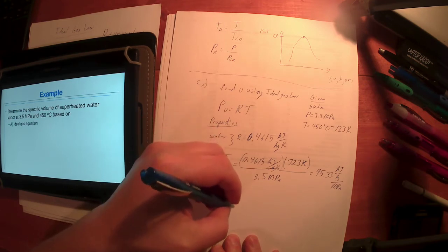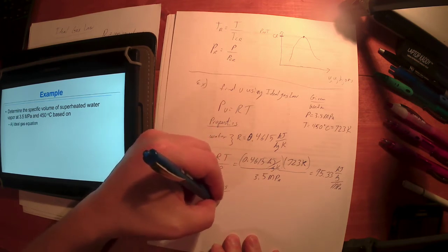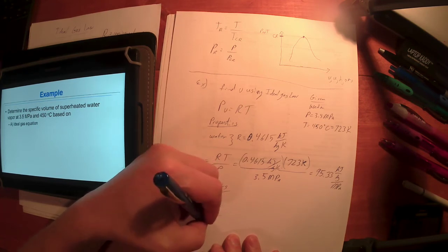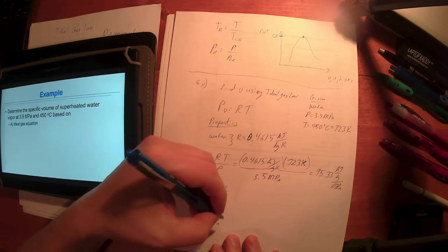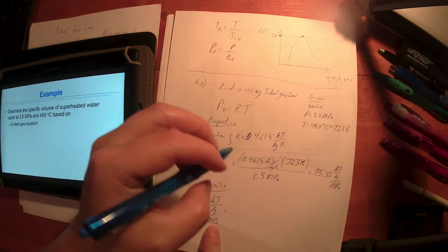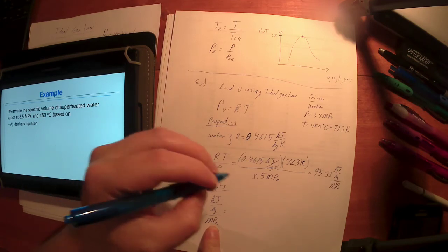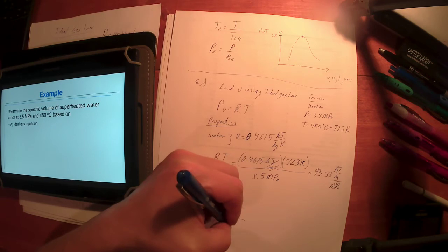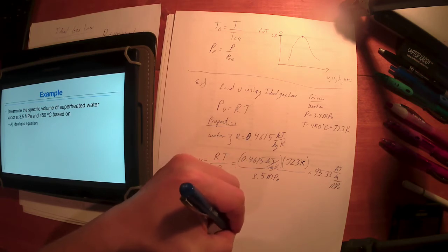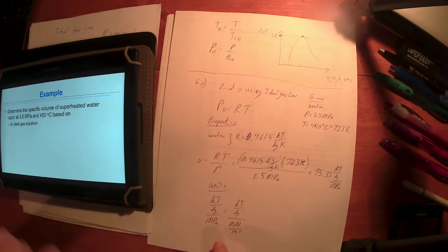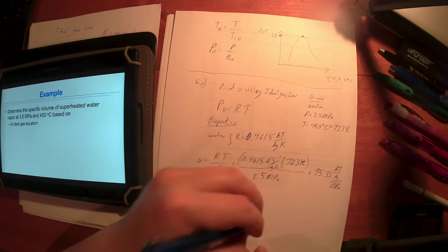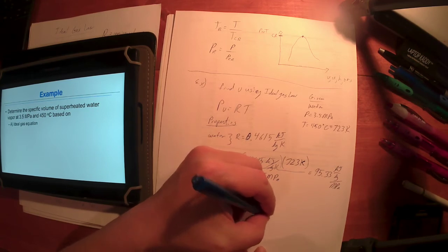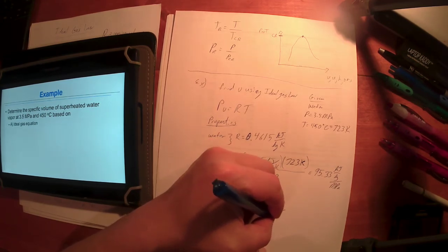Units. And as you guys are probably learning, if you're doing the homework right, you'll spend a lot of time trying to figure out your units. What the heck's wrong with that? So a megapascal, right? Now a pascal measures pressure. That's force per area. So a pascal is a Newton per meter squared. So this is kilojoules per kilogram over meganewton per meter squared. This is a complex fraction, so we're going to flip it over. So this is kilojoules per kilogram times meter squared per meganewton.